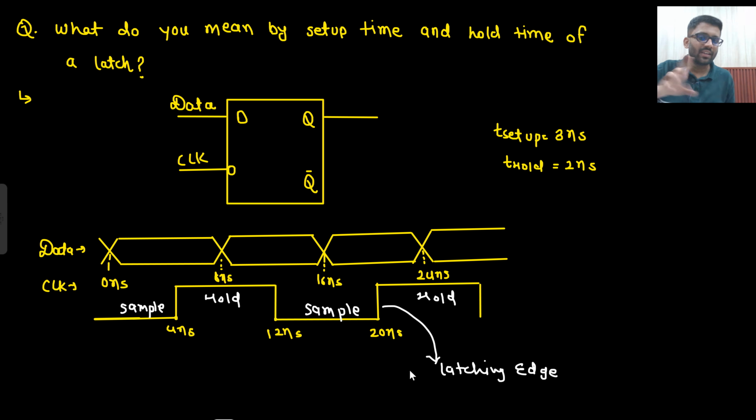Now at this latching edge, what will it see? Before and after. So before, 3 nanosecond setup time. Setup time means it will look before. So it should be stable for 3 nanosecond here, and after, for 2 nanosecond it should be stable.